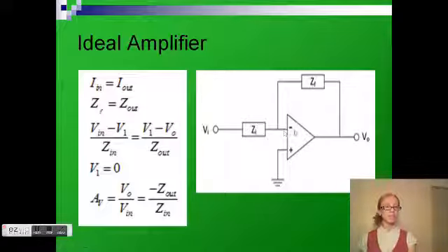There is no current that enters the op-amp. Because these input voltages are exactly the same, we assume that this one is also 0. So when we go to carry out our nodal analysis, as done in this situation, this current equals this current, and setting up our V-ins and V-outs, then we set this to 0 and we get our equivalent gain result, which also makes sense because it's negative, and it's going into the negative input terminal, so it's an inverting amplifier. What happens if it's non-ideal?